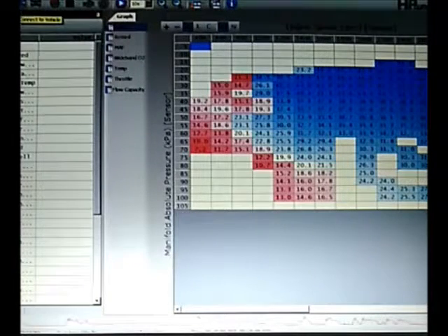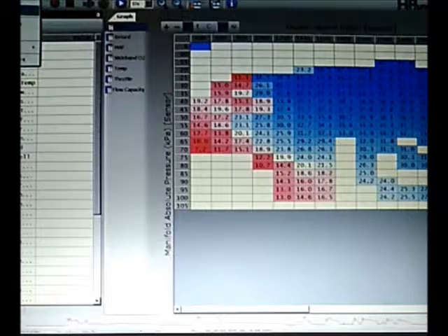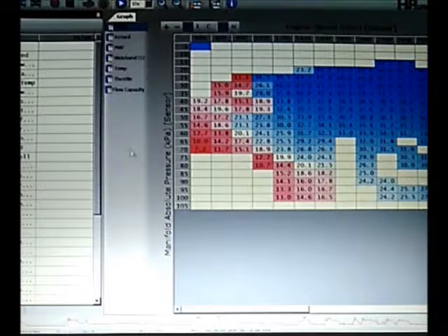and then disconnect, and then go to log file and go to close log file, because what that will do is blow away all your data and start with a fresh page. You don't want to sit in your driveway for 5 to 10 minutes screwing around with your graphs trying to get all your PIDs working and then take off and start recording values, because then you're going to be picking up a lot of garbage data from your driveway that you didn't want to be part of your scan. So start a new one at that point as soon as you leave and go for your actual drive, and then you'll be picking up mostly good data that's representative of how you would normally drive the car and not just idling in your driveway.